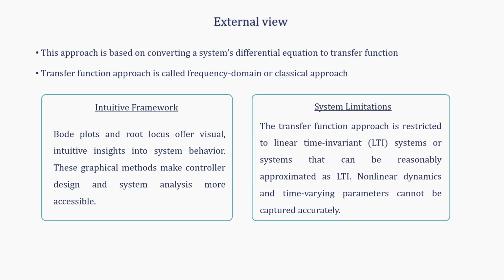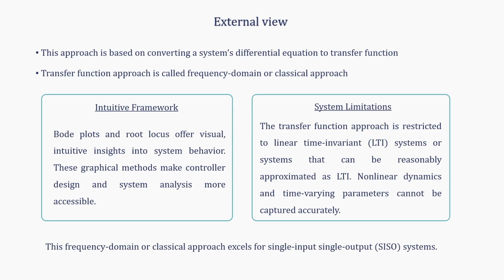However, there are limitations to this approach. The limitation is that transfer functions are generally restricted to linear time invariant systems, and if you want to apply them for the nonlinear case, then you will have to do certain approximations and only then use transfer functions. Further, this approach is limited to single input single output systems. Although you can come up with transfer matrices for multi input multi output systems, dealing with transfer matrices is not that intuitive. So, this is another limitation of the transfer function approach.